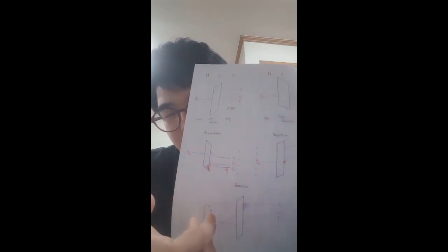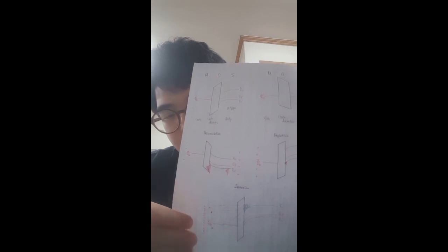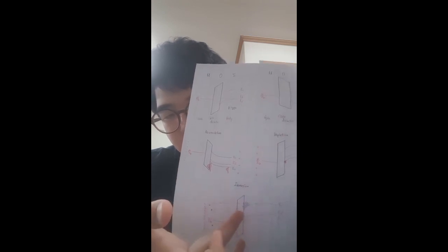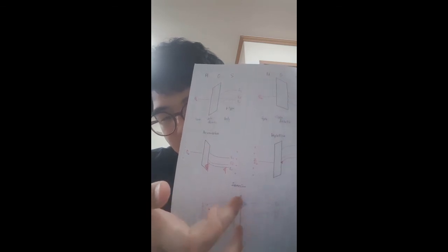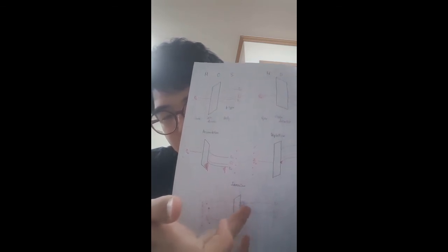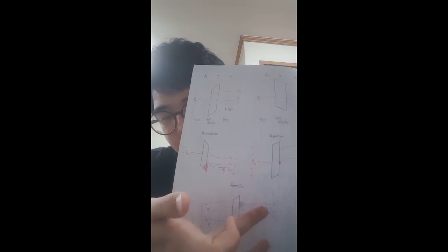We call this phenomenon inversion, and to make this condition, we should apply a bias bigger than the threshold voltage. The threshold voltage occurs when the potential difference between the conduction band and the Fermi level at the surface equals the potential difference between the Fermi level and the valence band in the body part.